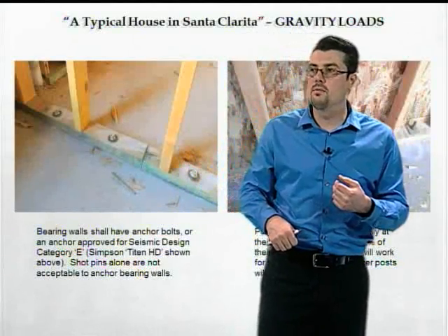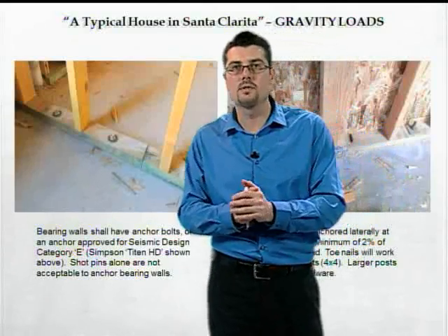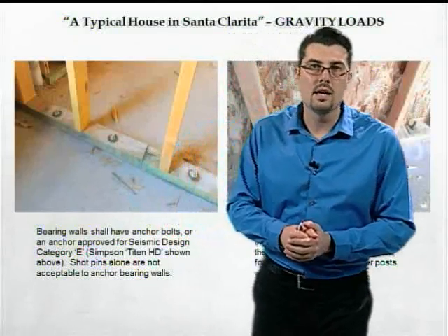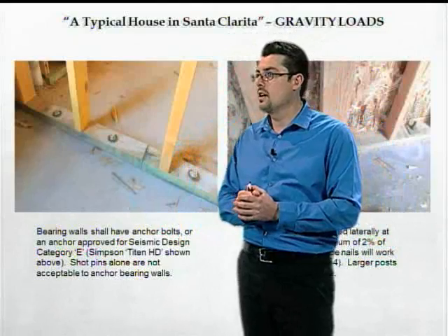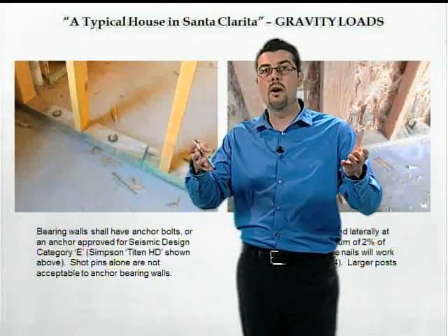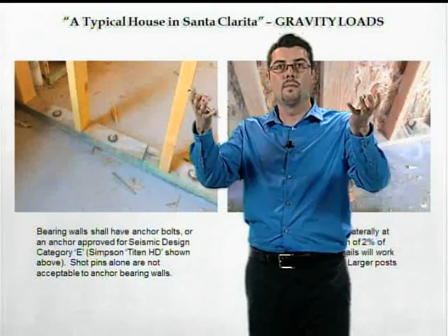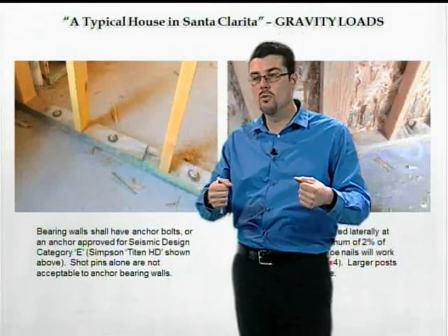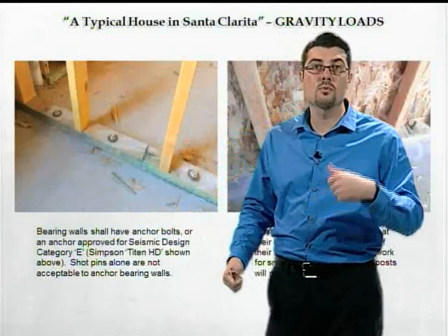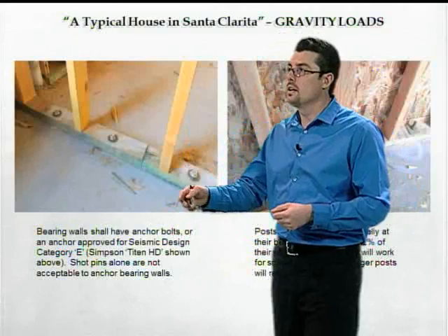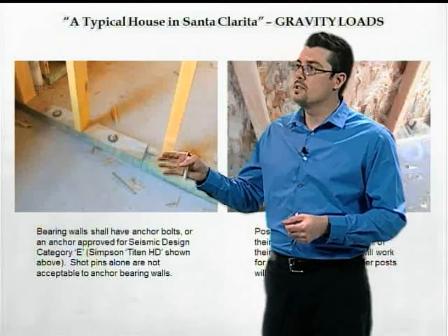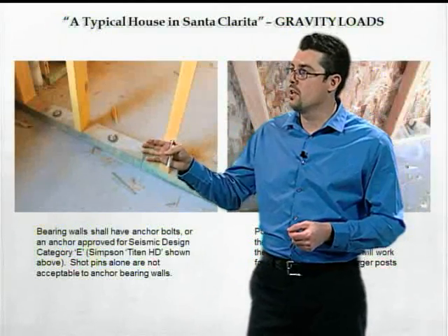In the 1994 earthquake, I was here in the city at that time, and in the damage in 1994, there were bearing walls that picked up and shifted and moved, and homes that came off of their foundations. And we had those problems here in Santa Clarita. And so there's a reason why the code does not want you anchoring a bearing wall with shot pins.